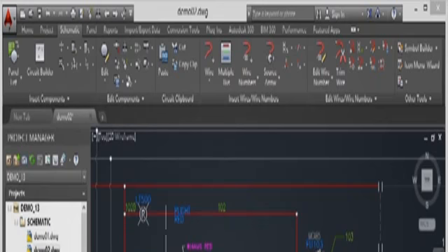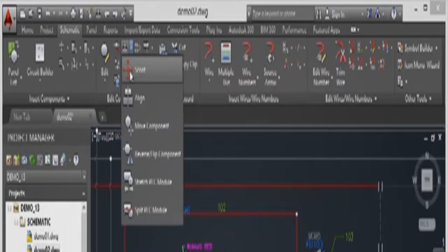Now you'll notice that my 102B wire number is a little bit cramped there. So what I might do there now is use Scoot and select that wire number there and just drag it along the wire. Now you'll notice I've got a problem. I've got a really tight little piece of wiring there now because I've moved that light along. I've aligned it. So how do I fix that? This does happen sometimes. Don't worry, just hit escape a couple of times to cancel that Scoot command.